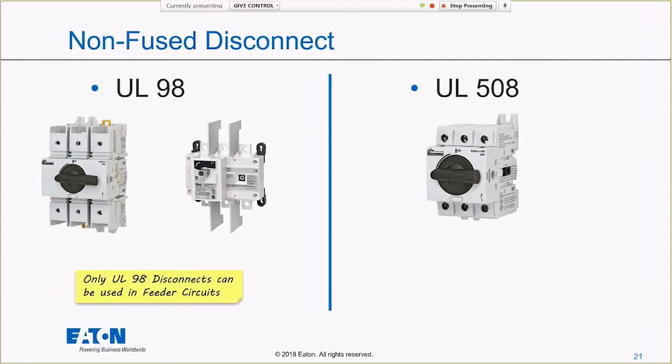They're rated for isolation. That's really the big thing, so it has provisions about the contacts not being permitted to weld during a short circuit, all of this. They are rated for isolation, which of course is exactly why you have a disconnect as your main disconnect in your panel in the first place. So it's an isolation rated disconnect.